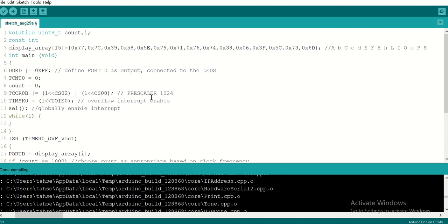In the timer section, there is one table which is named prescaler operation. Okay, prescaler selection basically. Inside this timer, there are some chip select pins, chip select 00, chip select 02. These two are responsible for selecting the highest or medium range prescaler, but it's advisable to use the highest prescaler, because the more prescaler you're using, the better delay function you can control, according to the theory of timer operation.